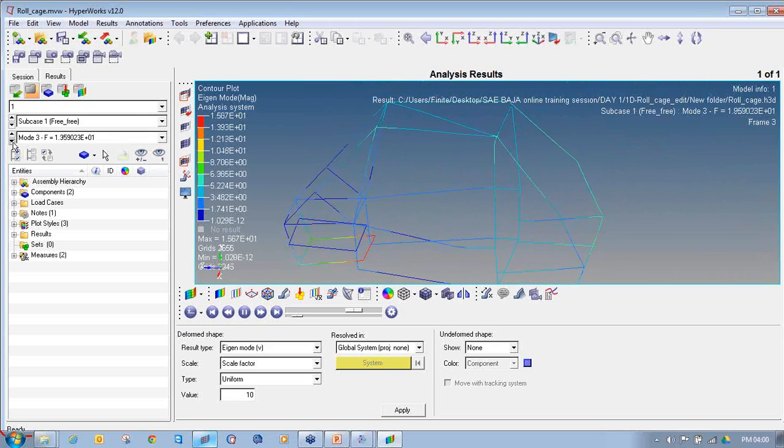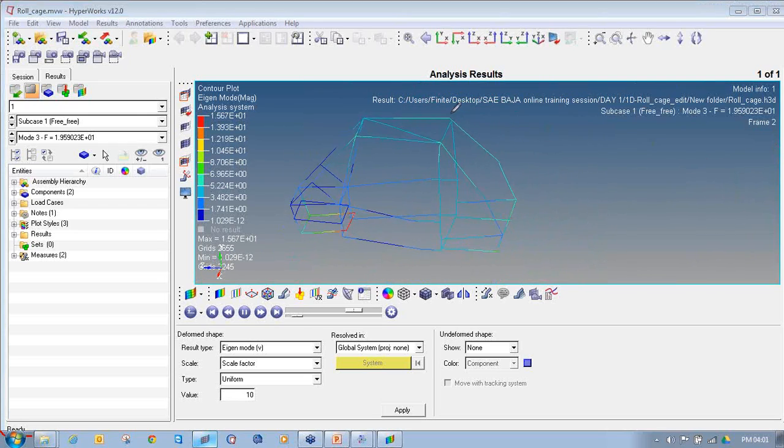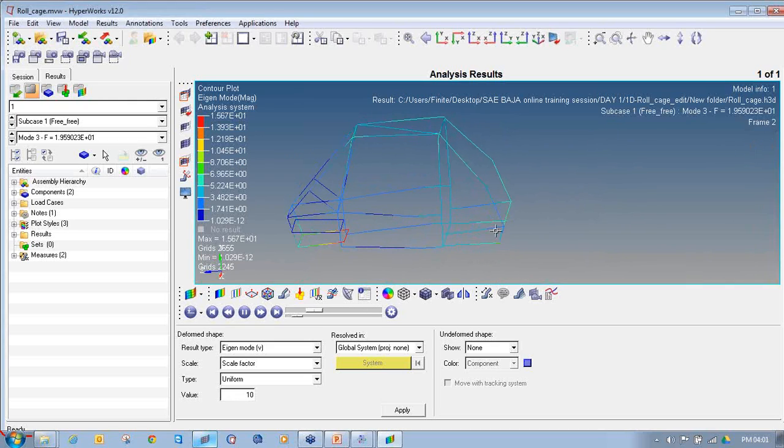So you can see here that this portion is not connected properly. This portion is not connected properly. So we will connect them again and perform a free run again. Here also at the end you can see these 2 bars are not connected. Even though it's the extension bar, this point is not connected to the extended bar. So there are 1, 2, 3, 4, 5, 6, 7, 8, 9 joints where the connectivity is not proper.